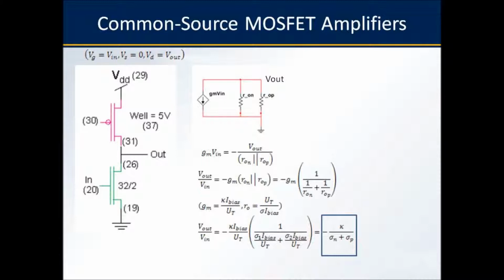What we have done here is remove the current source and put in its place a PFET biased to supply approximately the same amount of current. We can solve for the gain as we had done before by equating the currents to the FETs, but let's proceed by working out the small signal analysis. The equivalent small signal model is shown. KCL at the top node leads to this expression for the gain.